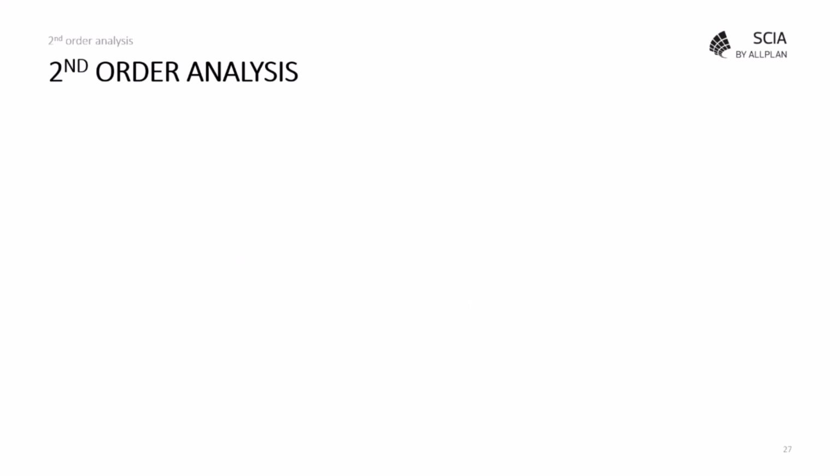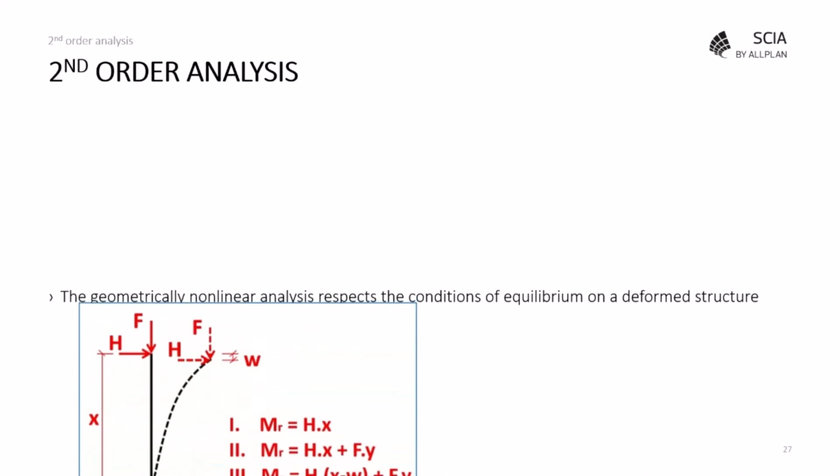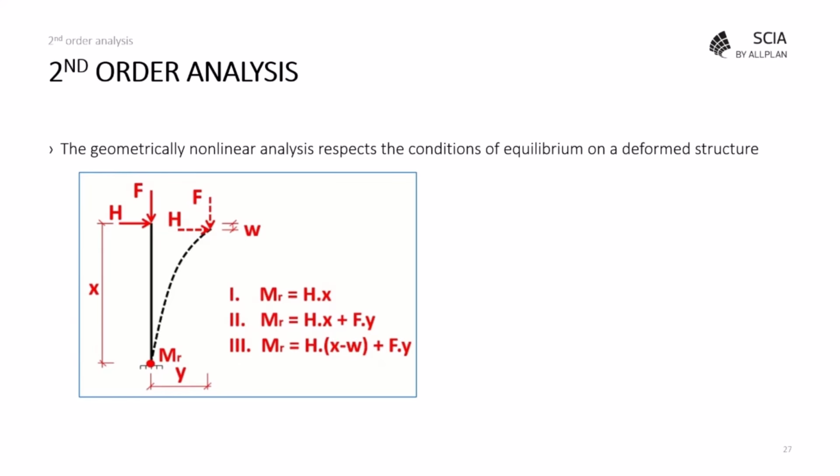When you have defined the imperfections, you can run the nonlinear analysis. And when you activate the functionality of the geometrical nonlinearity, you take into account second order effects. And important to know is that the geometrically nonlinear analysis always respects the conditions of equilibrium on a deformed structure.